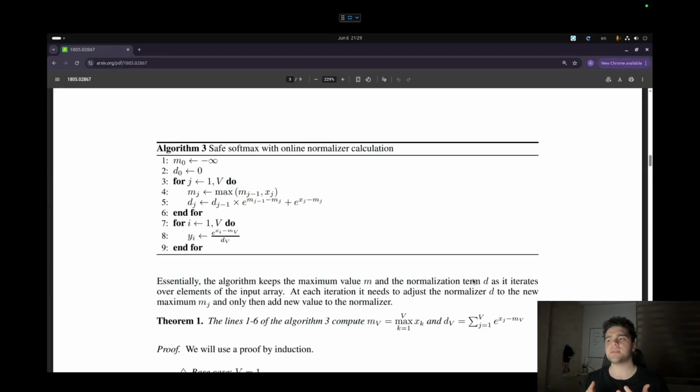Now coming to attention, the real bottleneck here is not matrix multiplication anymore, because we figured out an efficient way to reuse the data, to scale up our matrices, and just use bigger meshes to gain high throughput. However, the problem and bottleneck for attention is the softmax. The softmax needs to be calculated in an online manner, so we don't store the whole row in the accelerator itself, and we keep iterating in a fast way.